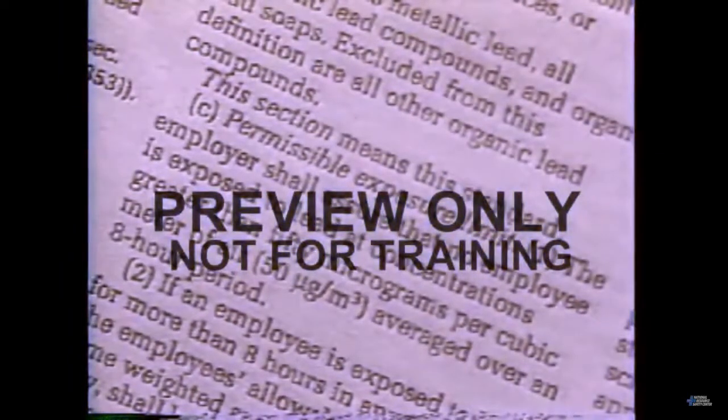Because of the harmful effects of lead, OSHA has set a permissible exposure limit, or PEL, of 50 micrograms of lead per cubic meter of air. The PEL is the maximum amount of airborne lead that workers are permitted to be exposed to over an 8-hour day. OSHA has also set an action level of 30 micrograms per cubic meter. The action level, which is lower than the PEL, is the airborne lead concentration at which an employer is required to take action by providing training and taking certain precautionary measures.